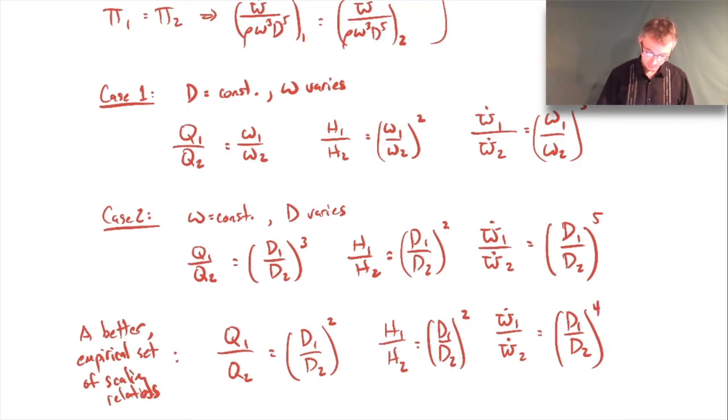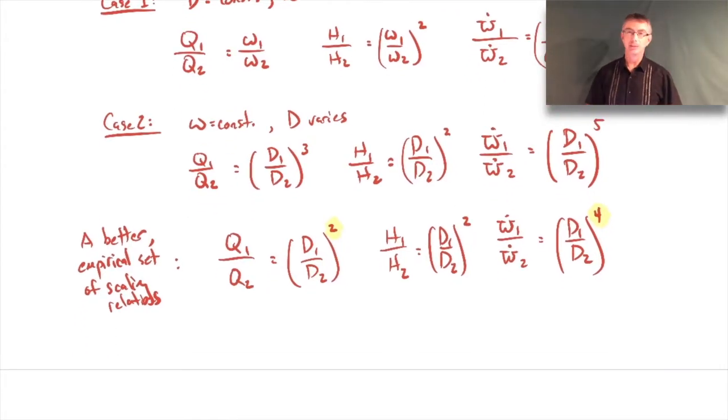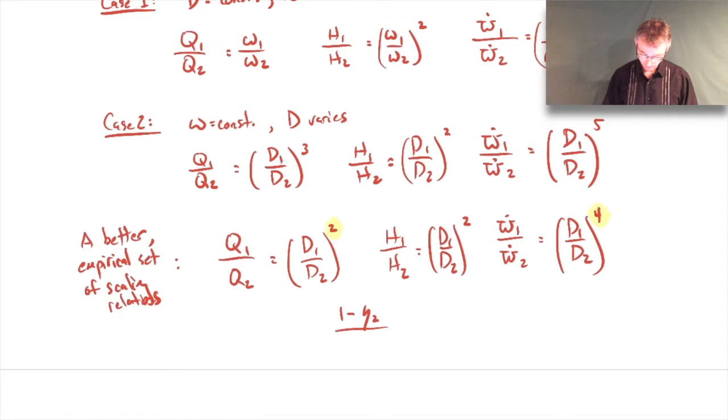So you can see that the difference really is just coming in here, in here. And that new set of scaling seems to work better. Again, rather than dimensional analysis, it really just comes from some experimental data. And then a better approximation for the efficiency, again, because we're not doing perfect geometric scaling, the efficiencies won't match up that well.